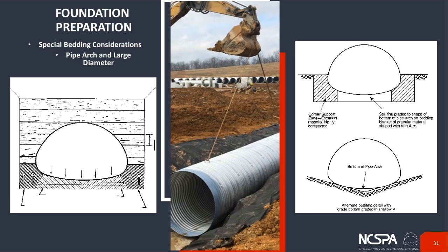And one more note when you're looking at these, because a lot of times with larger pipes, you're seeing them installed into wet applications, whether it be a stream or whatever. Most backfill operations are conducted dry, but you will run into the rare case where they are conducted in wet or submerged conditions. In these types of situations, a good quality granular backfill that really achieves its required strength when it's dumped into standing water should be specified, because you're obviously not going to get compaction in that soil if you've got heavy water.